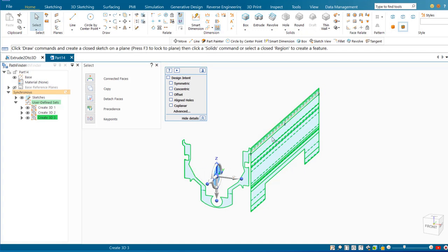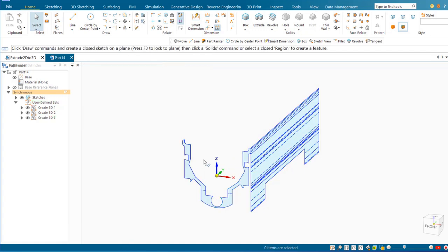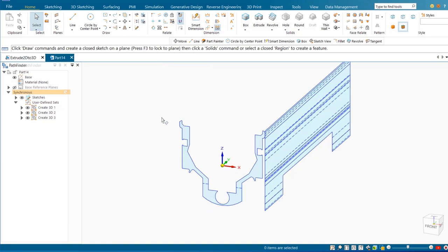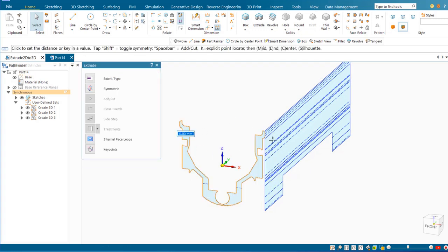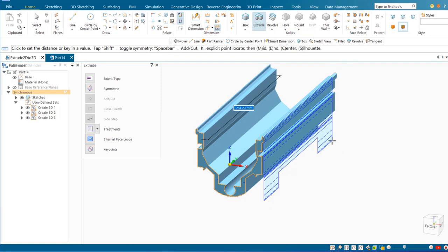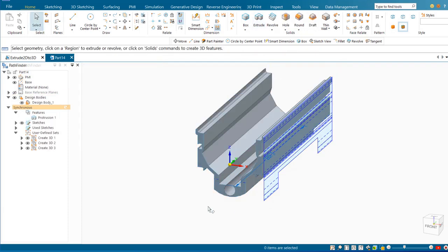And sometimes you need to move these profiles around with the wheel. I'm just going to hit Escape now. And I'll come down and identify these regions. Looks like it's not in one region, so I'll grab this first one, hold down the Control key, get the next one and the third one there. And now I'll push this back to that endpoint there from the side profile.